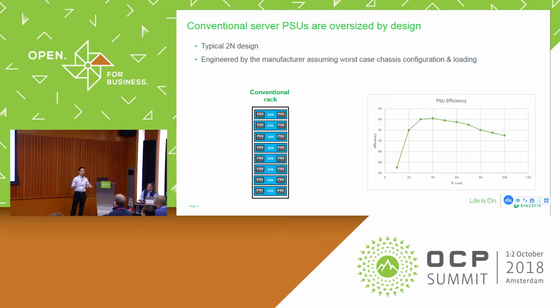It's not about N plus N redundancy, it's just what we call a safety factor, because sometimes you get overshoot in power usage. When you turn on your laptop or your servers, it's normally higher than normal use. We typically consider at least 50% higher than normal use, so typically we double the power supply unit design.